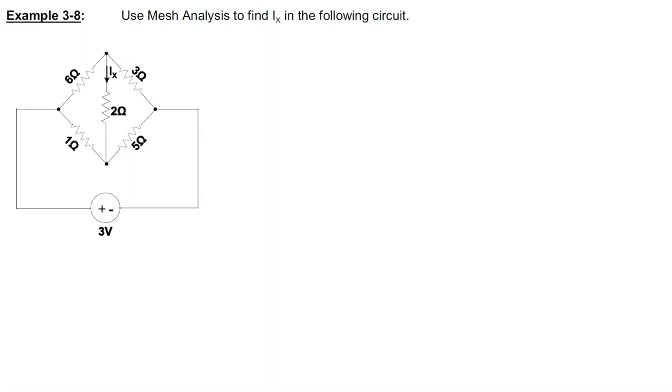Even though it only has one source, it cannot be solved by circuit reduction techniques, because no two of those 5 resistors are in series or parallel with each other. So you can't reduce that resistance using series-parallel rules. Some method of circuit analysis must be used to solve it. So KVL and KCL could be used. There are several closed loops that you can draw for that particular one.